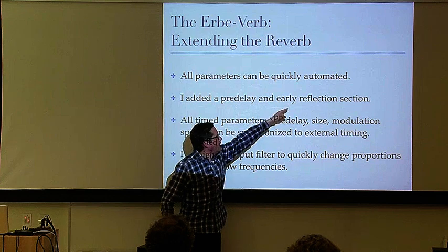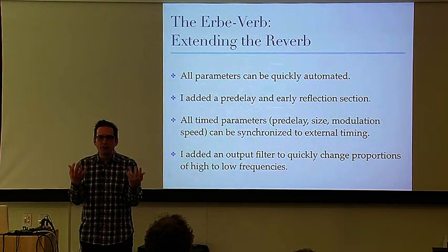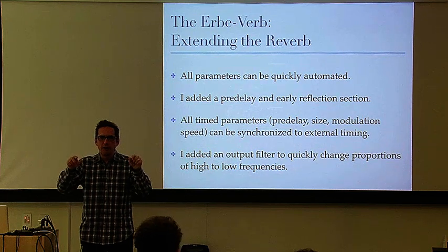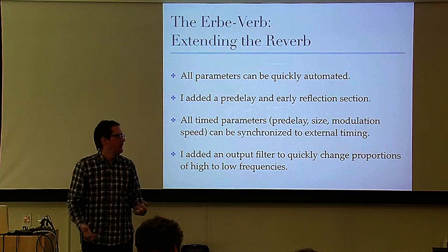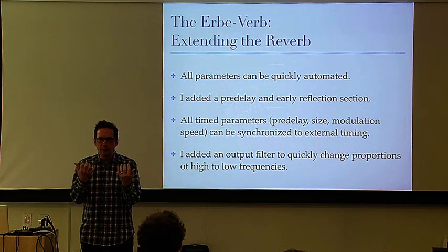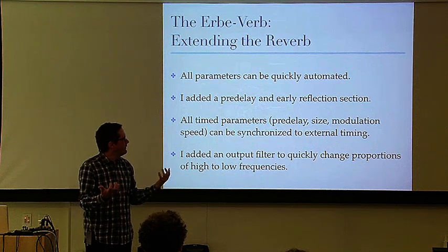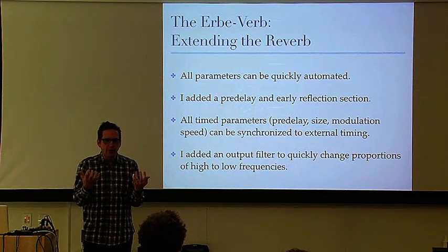And then the early reflections, this is just taking multiple taps off of all the delay lines, not just those 4 outputs, but taking multiple taps in each delay line and bringing them out. And you need to choose it so you're not doing any obvious comb filtering. You still have to pay attention to that. But what it does is it gives you quick, early complexity.